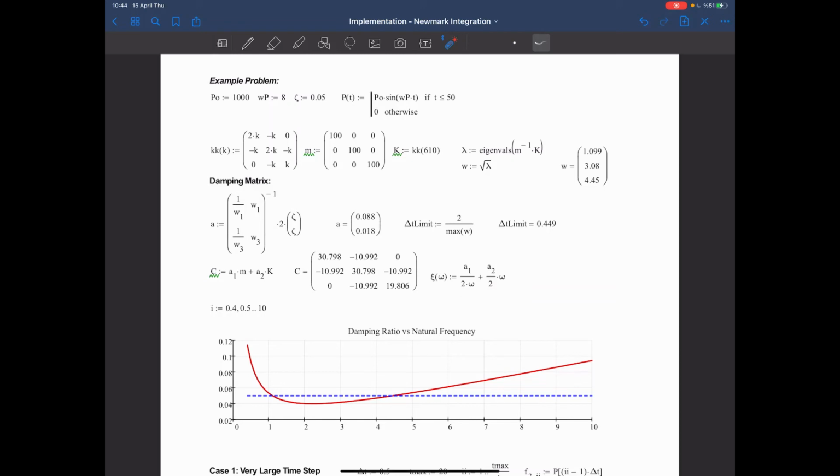So basically what we are trying to do here is we define an interval. In that case the interval is between 1.1 and 4.45, and this means that I'm really interested in the vibration within this frequency limit, because for frequencies smaller than 1.1 I got a rapid increase in the damping ratio which suppresses these vibrations, and after 4.45 the increase is not that rapid, it's linear, but again, for high frequencies, you get very high damping.